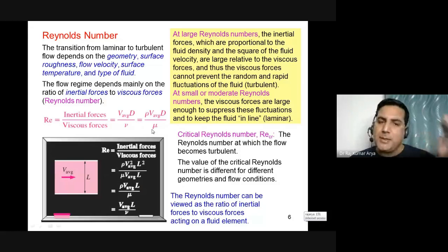So we say that you should have a Reynolds number greater than 10,000 to make it perfectly turbulent, so that you can get the correct flow rate from an orifice meter or venturi meter. So Reynolds number must be calculated all the time. Once it is calculated, he gave some numbers. Based on that, if the number is less than 2100 in a straight tube, then flow would be laminar. From 2100 to 2300, it is treated as transient, and 2300 onwards is treated as turbulent. Okay?